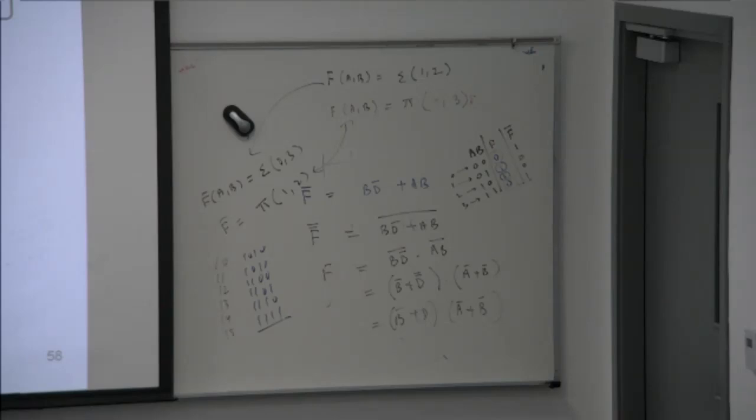We take the same example, the unreduced SOP expression. We take this, and we take this. How many literals? 6. Can you see here? Now we combine these two, and then we combine all the 4 corners. In the original expression, how many literals? 11. And this one? 6. All ones are covered or not? Yes. When all ones are covered, is anyone redundant? No. Nothing is redundant. We can proceed further.